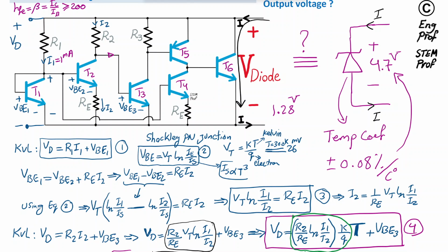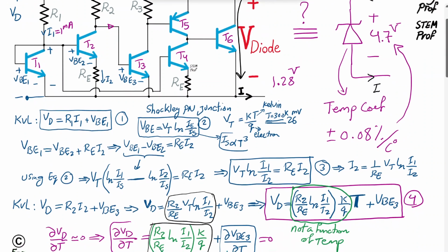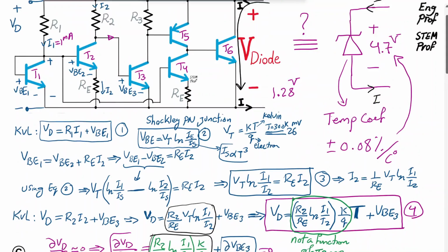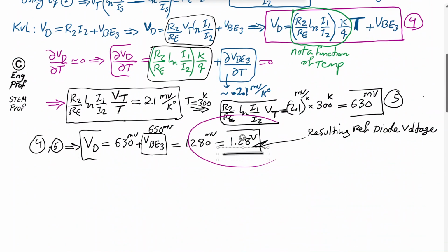So that's a reasonable assumption because the base current for these transistors will be considerably small compared to the branch current. And these HFE or beta assumptions that are practically valid are going to help us. Okay, so let's see what's going on then for the selection of components. As I said, I'm done with proving that we get 1.28 volt at the output of the circuit.